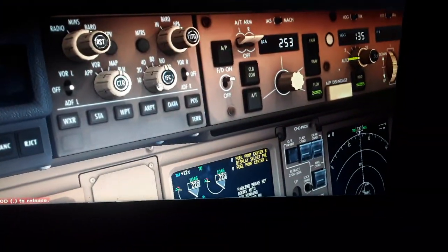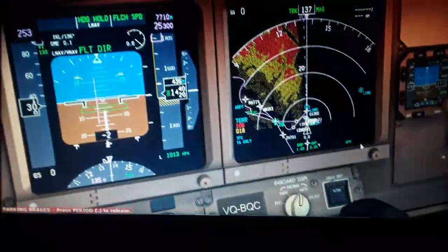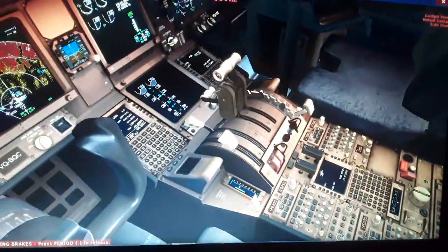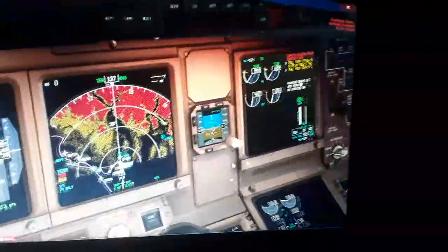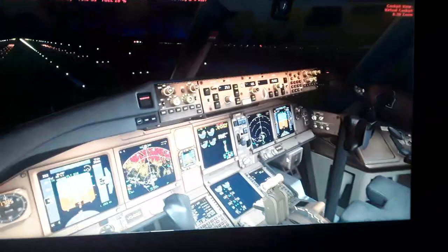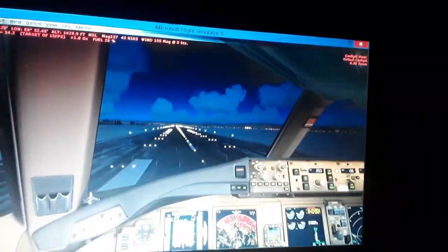Everything is set. Automatic commands, TLNAV, and we're going to have the nice scan for the radar. Flaps are set, and horizontal trim stabilizer set. So we advance the thrust levers, the takeoff position, disarm the parking brakes and go, and we have 18 minutes left for this flight.